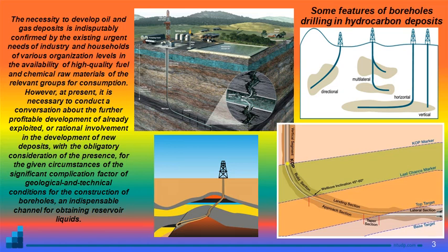The category of boreholes includes mine workings of circular cross-section, constructed in the layer of rocks and intended for the search, exploration and extraction of hydrocarbons: oil, natural and associated gas, gas condensate, etc. The borehole construction cycle consists of a large number of sequentially performed operations, among which the following main ones can be singled out: direct drilling of rocks, removal of destruction products, fixing unstable walls of the borehole, and creation of a reliable operational channel with correspondingly high rates of oil and gas extraction from productive layers.